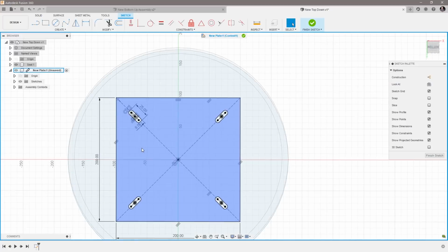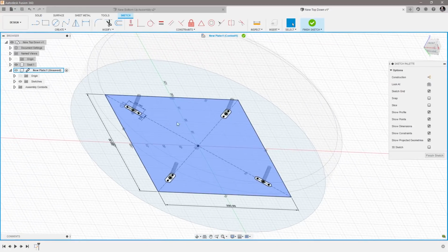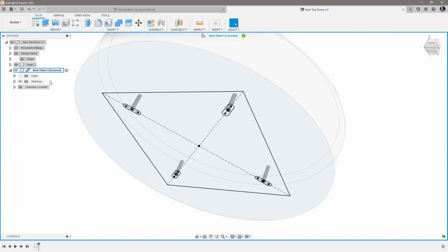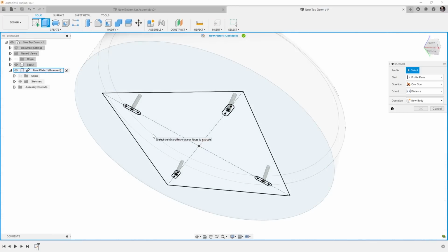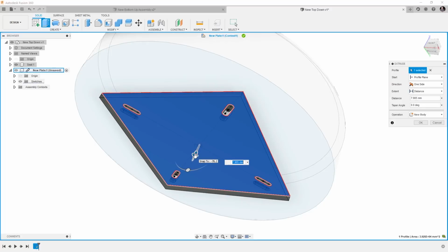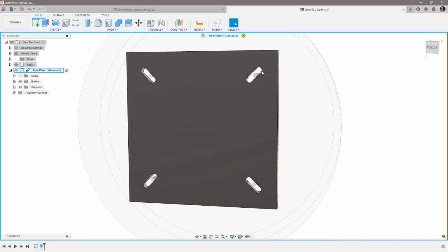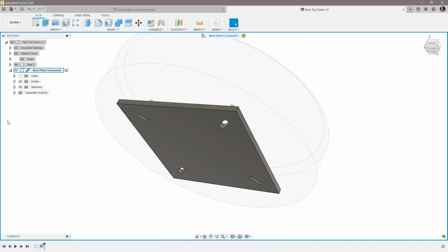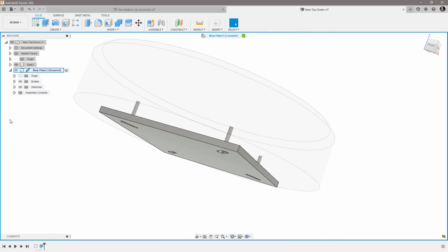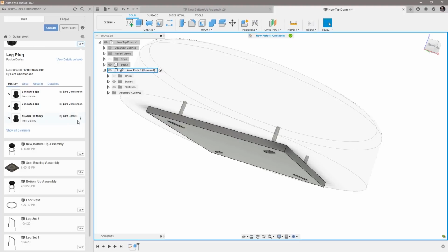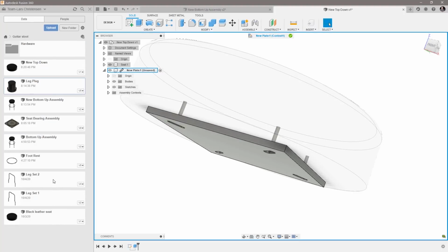And we know that they are in the right area. So when I finish the sketch and I hit the extrude, we can be certain that this plate here is in the right location for those holes. So that is the nice thing about this top down. Now, this one is linked out, but you will actually not see it in my list until I save this document.